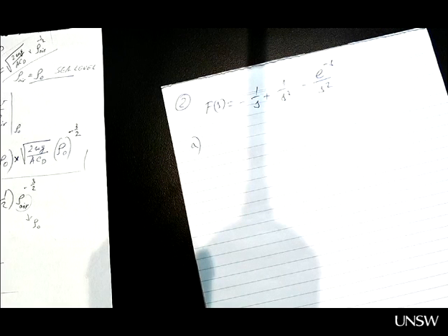A longer way is to find f of t, the inverse Laplace transform of f of s. Find f of t, then make time equal to infinity, that will be the final value. Make time equal to 0, that will be the initial value. A quicker way is to use the initial and final value theorems.